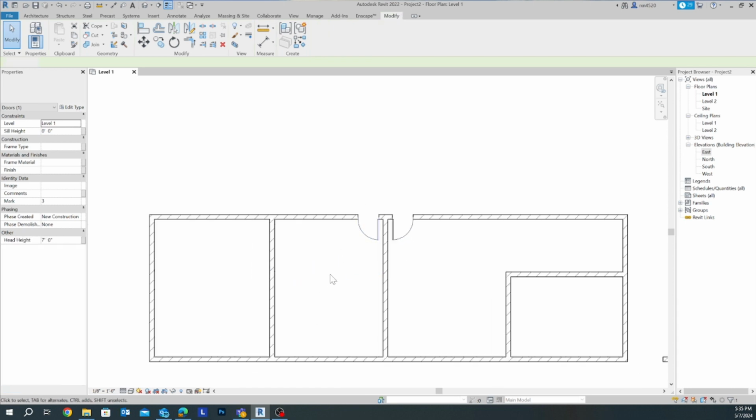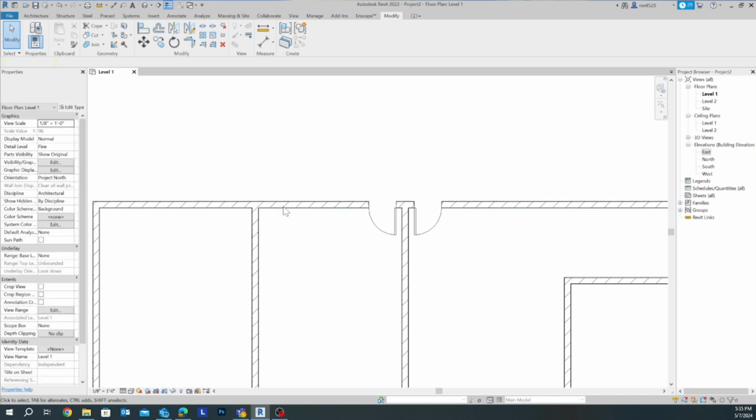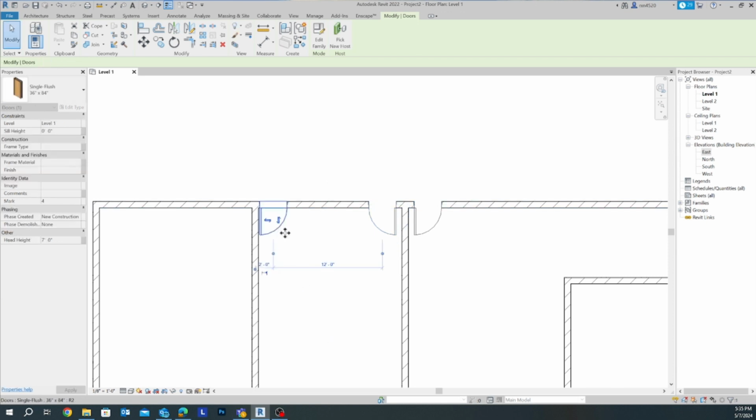Now what if you need to create a door somewhere over here? For that, you're going to use this mirror draw axis. This was pick axis, this is the draw axis mirror tool. You click on this mirror, click on this door, press enter, and then from the center line of this one, or anywhere if you want, say at 8 feet, you just click. Basically you're creating a line and then using the mirror tool to create this particular door.